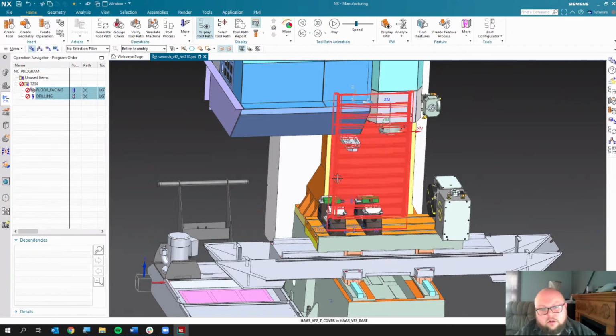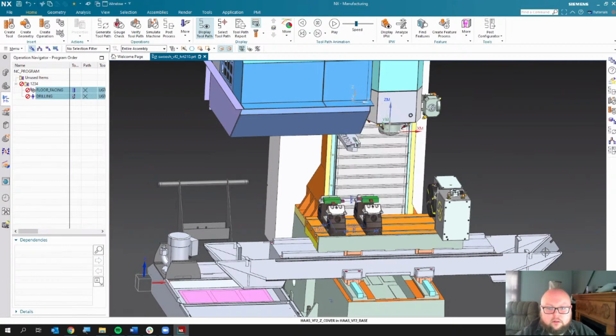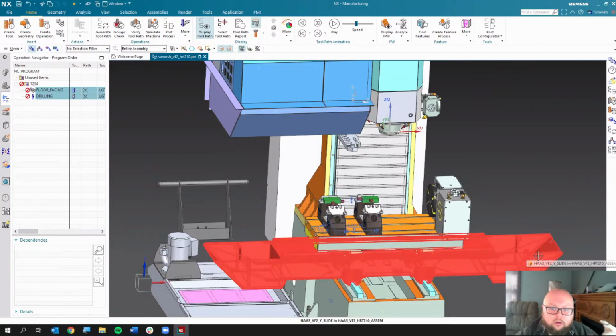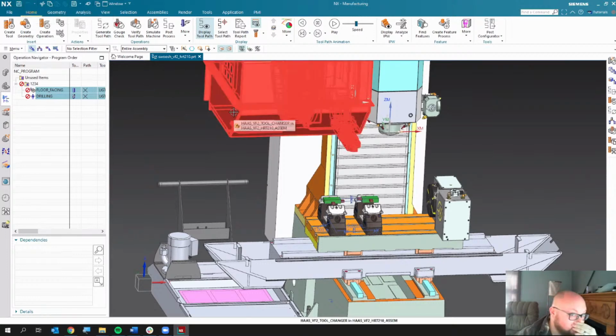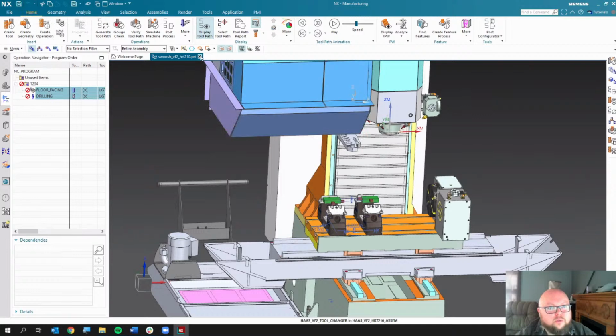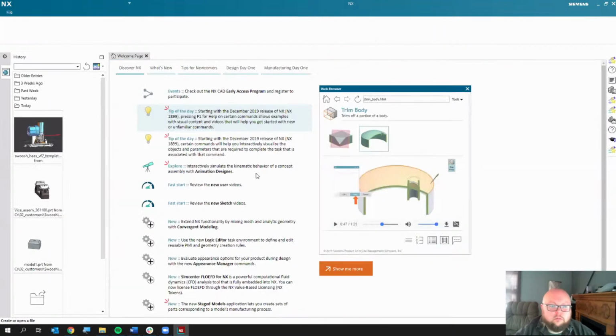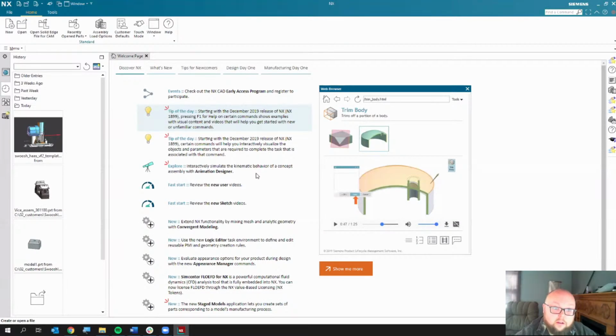All right. So now we've gone through, we've created, we've added our machine tool, we've positioned our target bodies, and we've created a couple operations and tooling. So that's great. That's a great starting point. So I'll go ahead and save this file again. And I'm going to close it at this point in time. So really our PAX file has been created, and we've created our custom template for this machine and this particular setup.